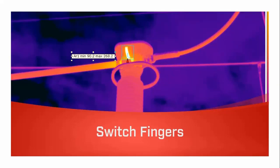This is a high voltage air switch. Where the area box is, the little green square, we can see one finger of the switch receiver looking quite warm. And with the current levels very high on these units, the potential to have a major issue is ever present. Just remember that in a parallel connection, which is what these fingers represent, the hot one is the good one.